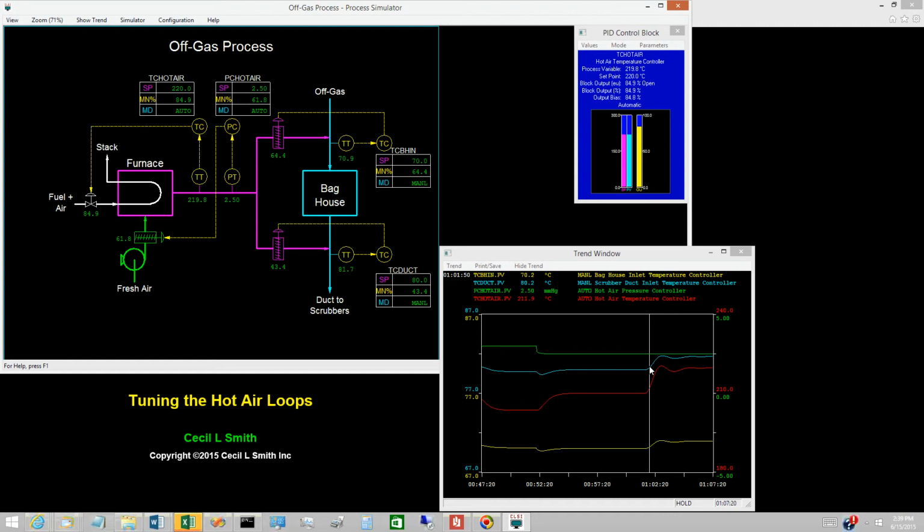What about the controller gain? The overshoot is modest, and the oscillation is barely visible. No need to decrease the controller gain. Increasing the controller gain would increase both the overshoot and the oscillatory component of the response. Let's go with what we have.